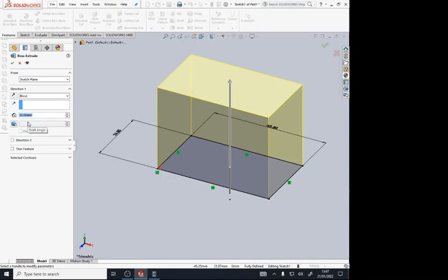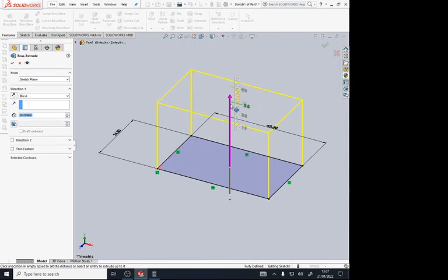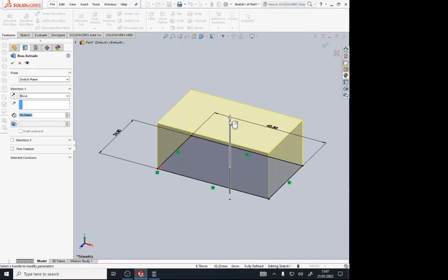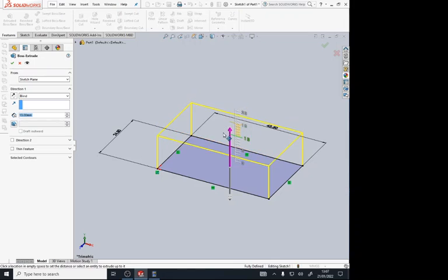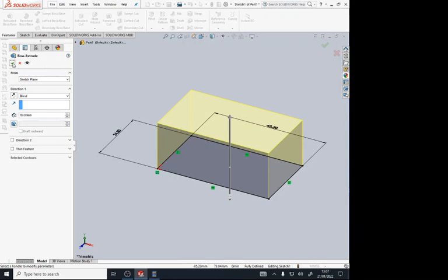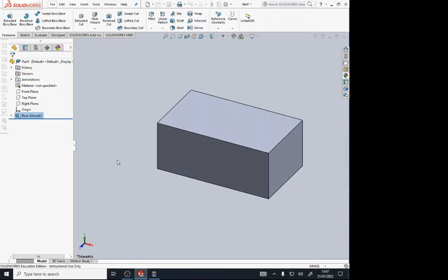So the dimension that we need to go to is going to be the same thickness as the wood which this piece is going to sit within. It's the veneered MDF which you were working on earlier, or you will come to work on in the workshop. This wood is 18mm thick, so either using this sliding function or alternatively over here on the side, adjust it to 18. You can see that's there. I'm happy with that. Press tick and job done. You've gone from taking something which is 2D to 3D. Perfect. We're on our way to creating the fitting that we're looking for at the very end.